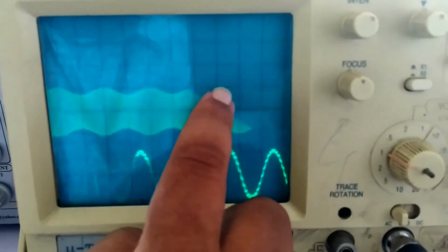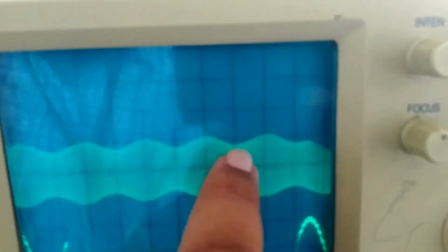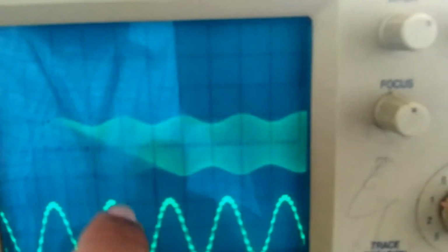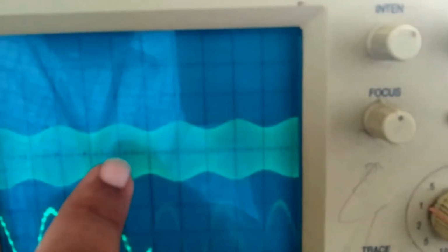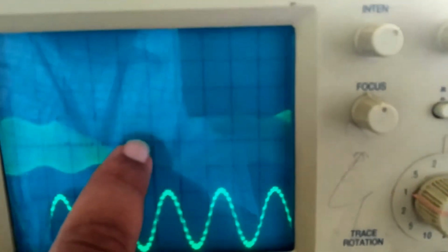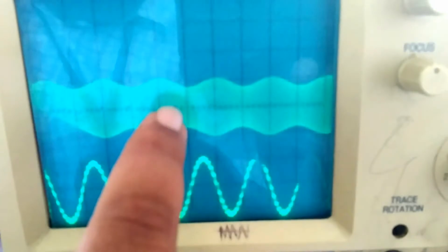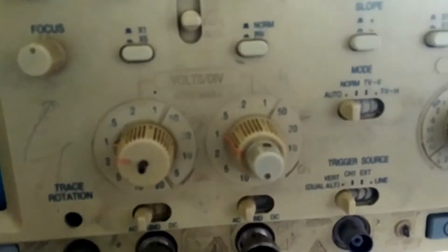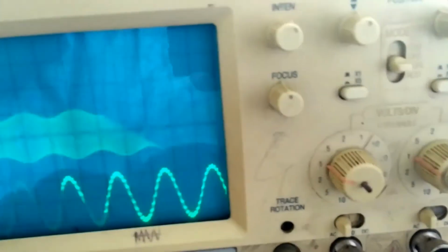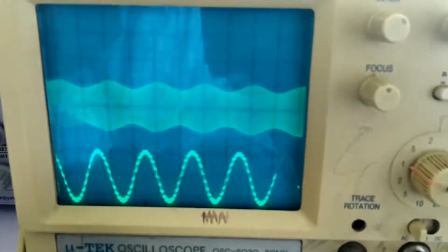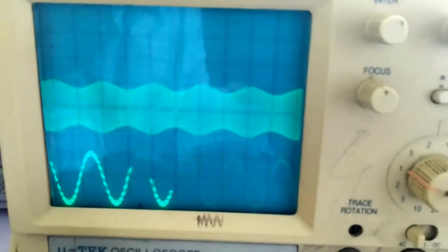And similarly, you can see A minimum occurs at around 0.7, because every unit is divided into 5 parts. So a subunit is 0.2 volts or 0.2 units. So here it is 0.7 units, 0.7 into 1. That's 0.7. A maximum is equal to 1.1 volt and A minimum is 0.7 volt, so that we can calculate the modulation index, M value.